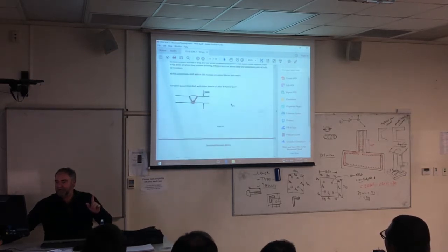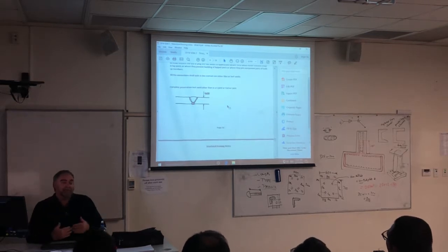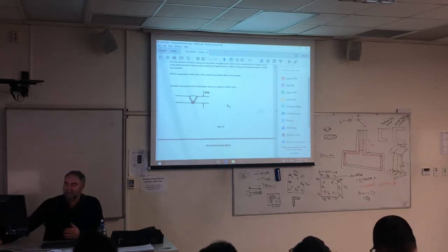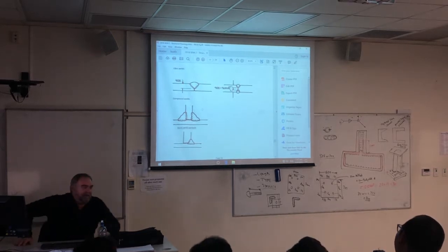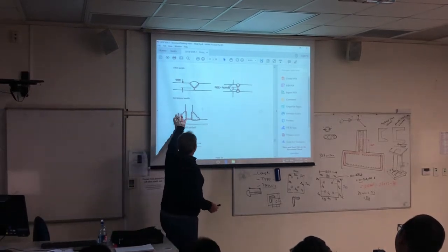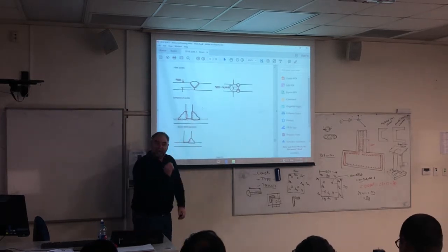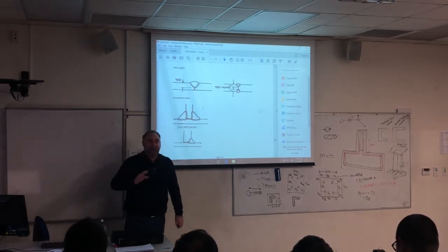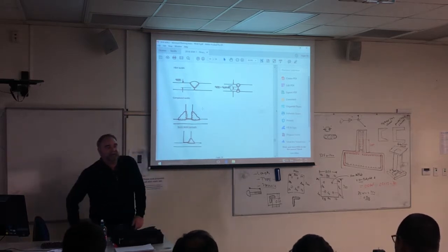Now I'm going to show you some, starting with what a weld looks like. So we use welding as a way of joining up 2 pieces of metal, but it doesn't necessarily mean it's stronger. When we talk about a 6mm weld, we're talking about the width of this piece here. So it doesn't necessarily mean it's perfectly 6mm all the way along, but the welders, and you can get some very, very good welders, their aim is to try and stick to that approximate dimension.